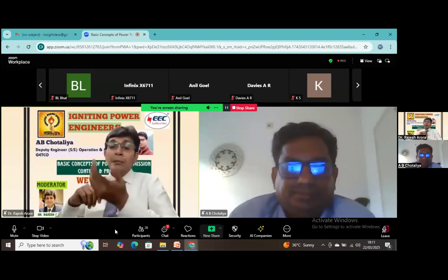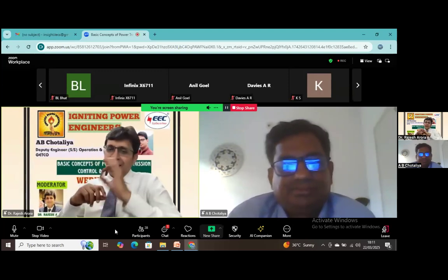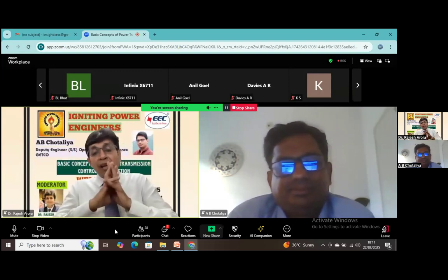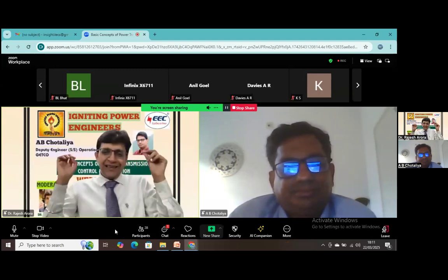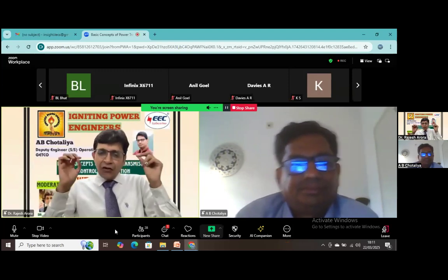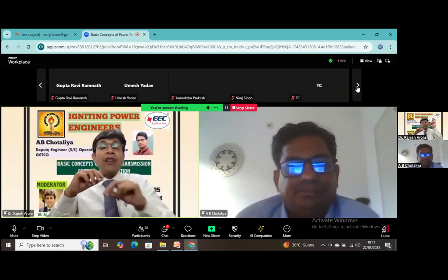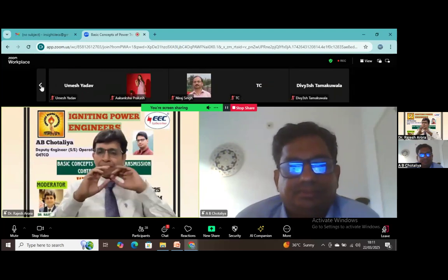And a very important part you mentioned, trip circuit supervision, 95. That plays a vital role because the tripping circuit of the breaker should always be ready to take a command from any relay. And that should always be ready for that command, and that can be supervised by a supervision relay. Very beautifully explained all the aspects.